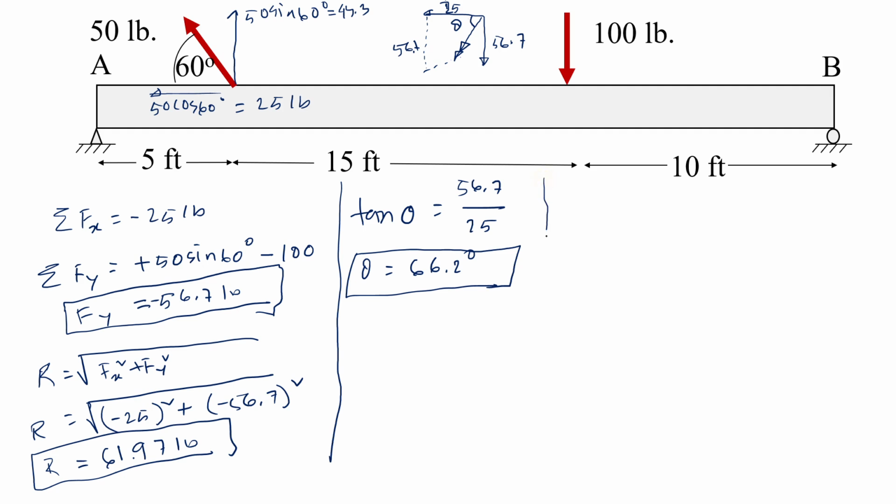We also need to find out now, the surprising piece, which is the location of this force. We don't know which way it's going to act. I'm going to assume simply somewhere in the middle. Typically, that's probably the most logical way of thinking, that it's going to act somewhere in the middle of these two forces, which we'll find out is not so. To calculate the location, we'll have to apply the Varignon theorem, which states that all the component force moments will be the same as the resultant force moment.